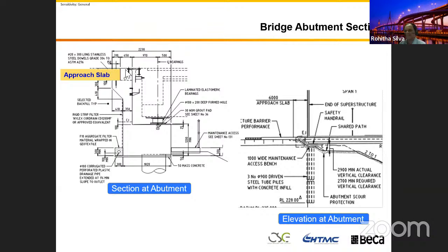If you use a finger plate joint in this particular drawing, the picture you can see is a finger plate joint. The water will come through this one. Then you need to have a bucket to collect this water. These are minute details, but it's really required to get the performance right. Otherwise, if you use just a standard one, you can have spill through the batter elevation. Show it in here.